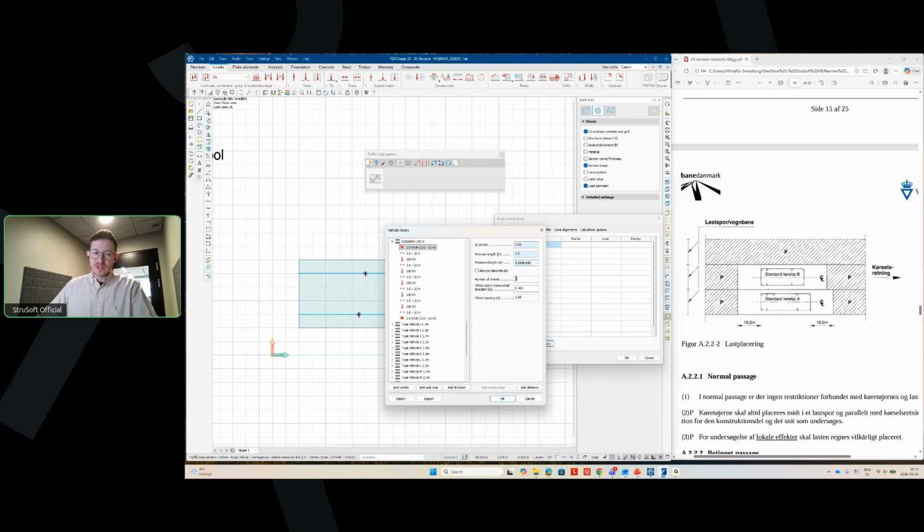The number of wheels here is a bit strange maybe, but we will set this to 1 wheel that is 3 meters wide. So here we are creating one big surface load basically. And the wheel spacing will not really matter for just 1 wheel. So that's it. Then we keep going. This one is 10 meters long. This one, let's just keep it to 100 kilonewtons. Let's just keep all of these other options for the axle loads as the set options.